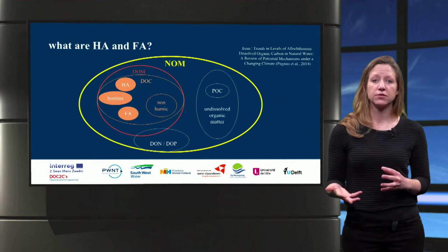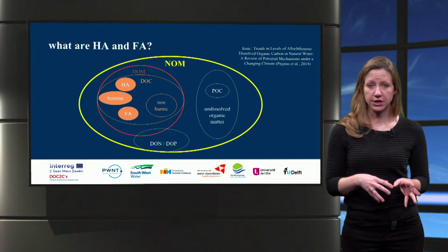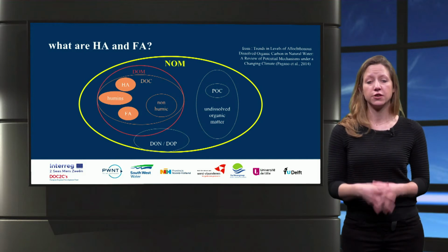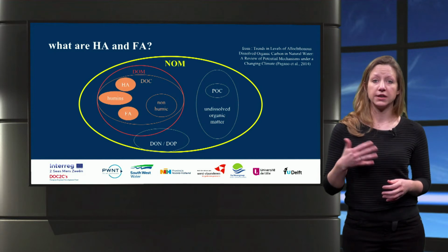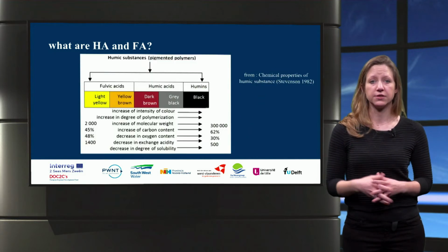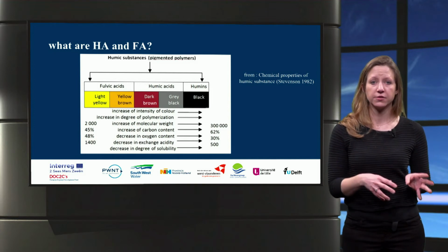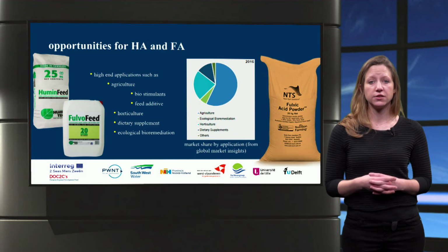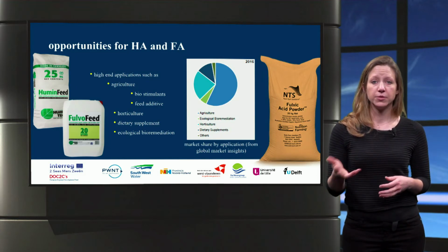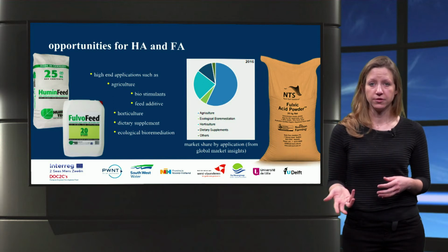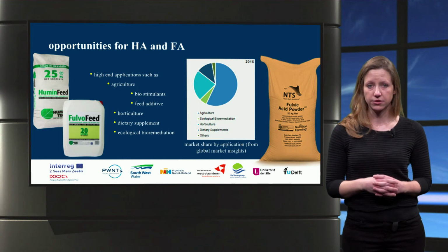As part of the natural organic matter, and subsequently of the dissolved organic matter and the dissolved organic carbon, are two specific species, the humic and the fulvic acid. Thanks to their low molecular weight and high numbers of carboxylic and other active groups, they are a prime target on the ion exchange and end up as a dominant part of the natural matter in the brine. In addition to adsorbing well on the resin, the previously mentioned properties give the humic and the fulvic acids an important market value, being a natural chelating agent in various industries such as agriculture.